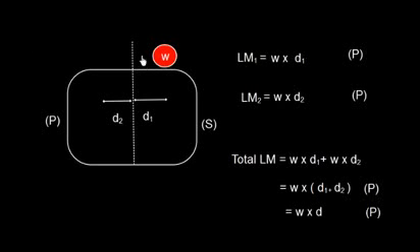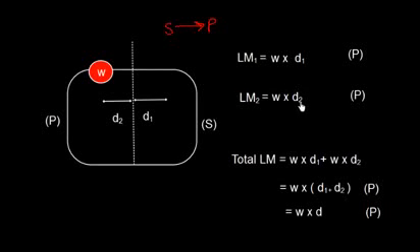So now let us consider the scenario. I shift some weight from here to here, from starboard to port. So first let us consider I pick up this weight. So this is as good as I discharge the weight. So list moment will be w into d1. Similarly, when I shift this weight, so I discharge from here and I put this weight here, the list moment 2 will be w into d2, where d1 is the distance of shift from this, and d2 is this distance. So d1, this is the center line, so the total distance will be d1 plus d2.